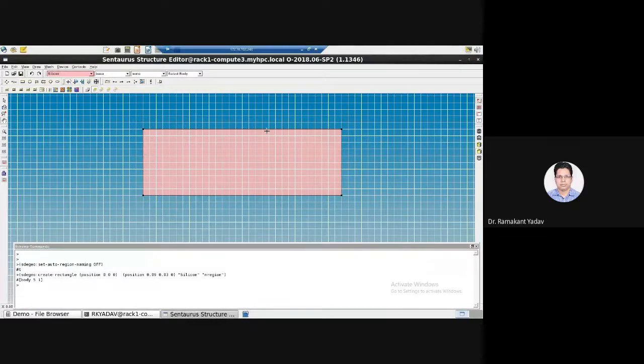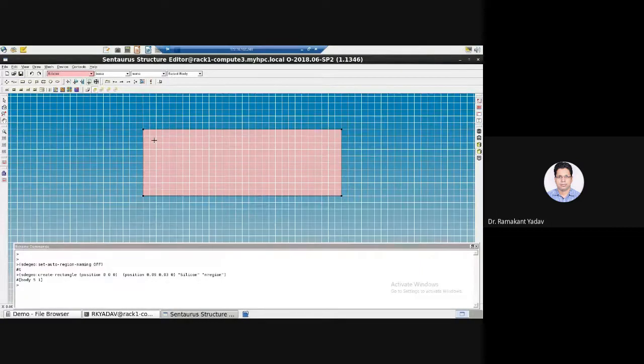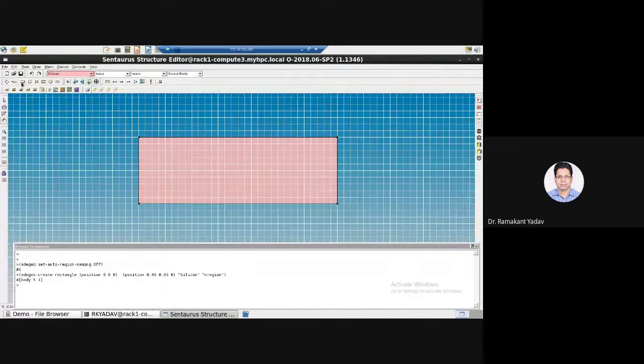So students, whenever you have doubts, you can just unmute your microphone and stop me. I will be continuing from here. We have created the N region. In the diode we have two regions, P region and N region, so let's create the P region inside this. Now select this snap to grid. Select the region, sorry, select this rectangular region. Now you can create this.